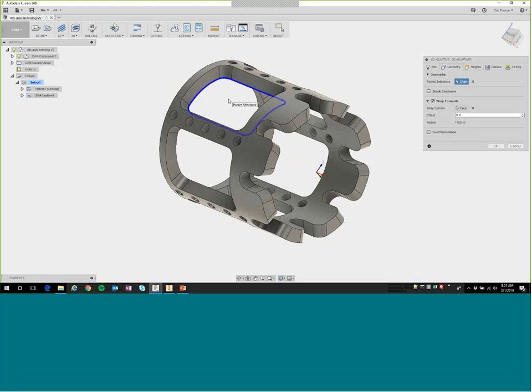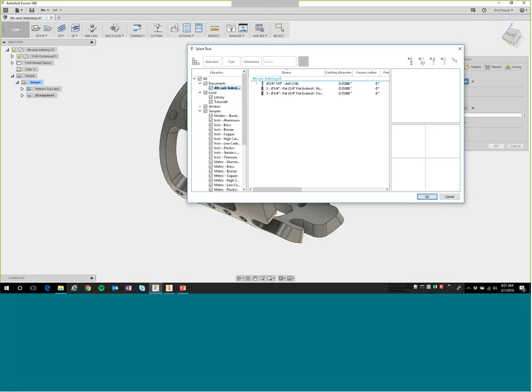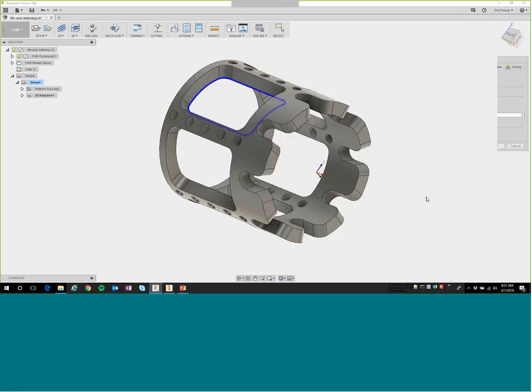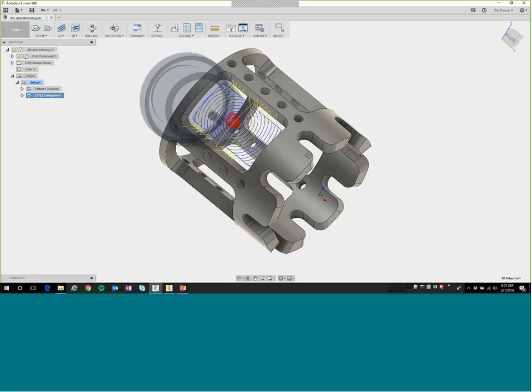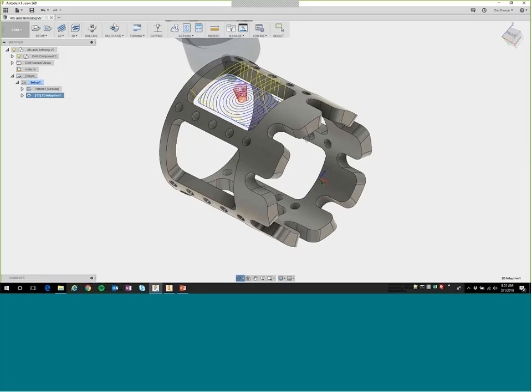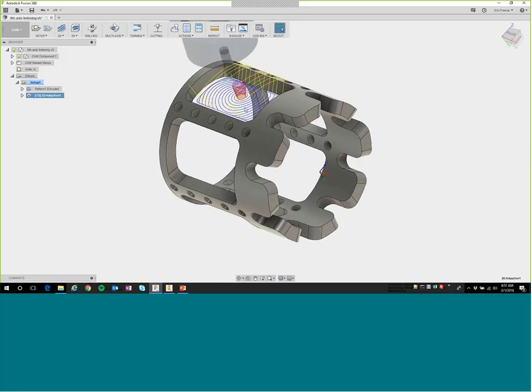So we'll go ahead and get that created along the top. Checking to make sure I've got everything in there. I think that works, so we'll go ahead and accept that. Oh, yeah, sorry, need the tool. Use the roughing tool to do that. But it goes through and identifies the information that goes along with our model. So we've got a roughing operation, and now we want to go through and clear that out, right? We want to finish it out and actually break through.